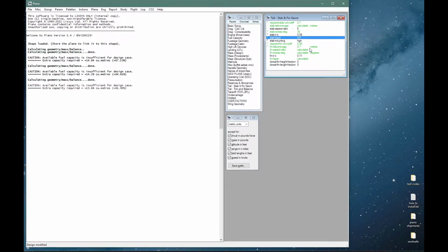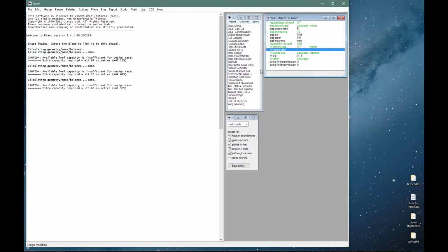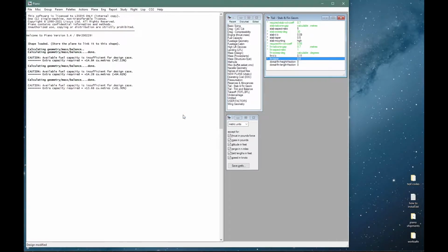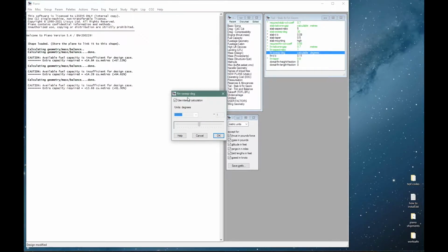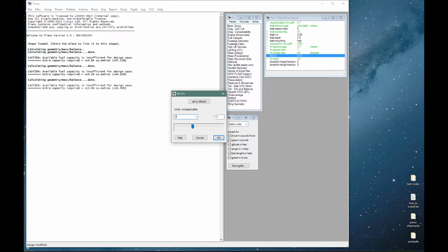The fin shape is complex with a large top fairing for jacks and stabilizer trim mechanisms, but in broad terms, fin aspect ratio is around 1 and fin taper ratio around 0.8. Fin sweep back 45 degrees and 9% again for the T over C.